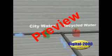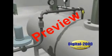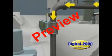The CSB believes that operators later shut off the city supply, opened the valve to the recycled water line, but then, for some reason, delayed switching on the flow of recycled water. Without water pressure, acetylene began to flow backward from the generator. The check valve was the only remaining safeguard to prevent acetylene from reaching the open drain in the shed.